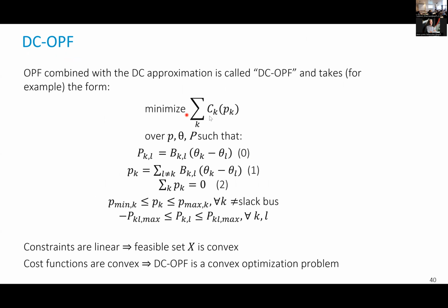So the DC OPF ignores totally 2 things: the power losses, but also the reactive power. So any constraints that involve reactive power or imaginary parts of currents are not acceptable. So typically we replace the power constraints on the line, which are in apparent power, or more exactly even on current, a complex current, by constraints on maximum power on the lines here. So we assume we admit only some maximum active power flow on the line, which is only an approximation of the true constraint.